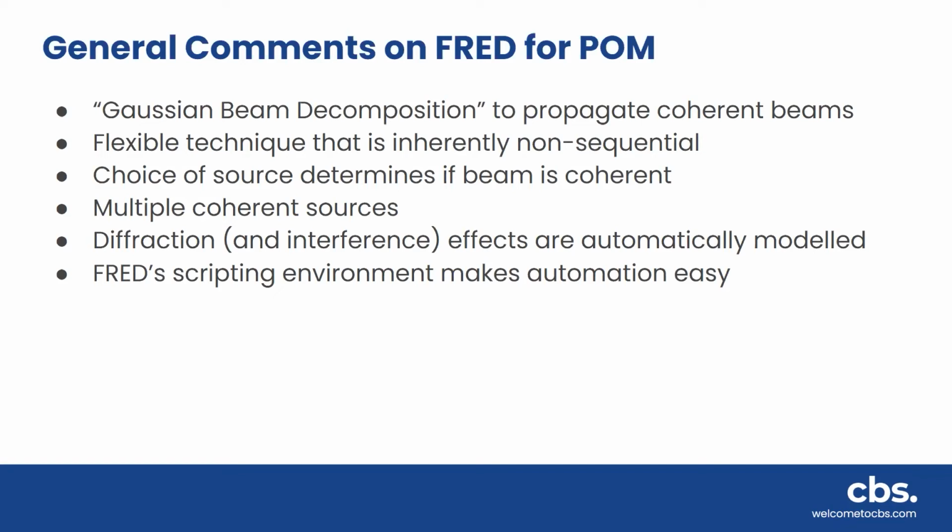Fred uses a technique called Gaussian beam decomposition, which allows us to leverage the ray trace engine that is already inside Fred. It's a flexible technique that's inherently non-sequential. And the choice of source, whether you use a coherent source or an incoherent one, determines if the beam is coherent. There are multiple coherent source types, and diffraction and interference effects are automatically included in the calculation. And Fred's scripting environment makes automation and tolerancing and things like that incredibly easy.